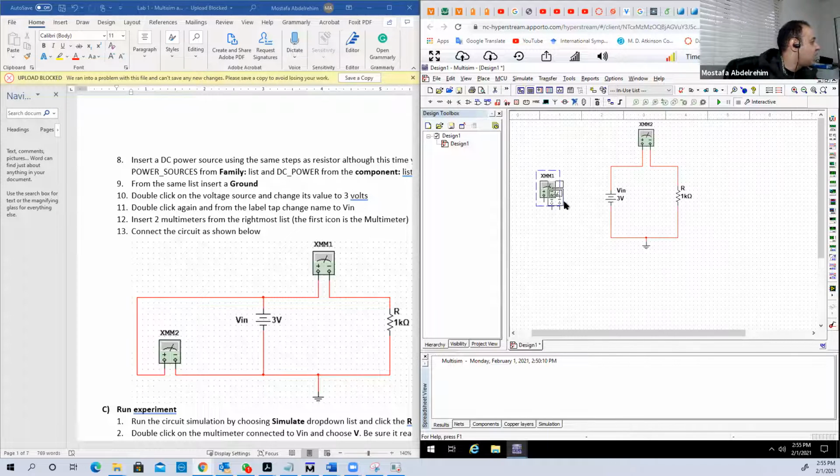One last thing is we're going to connect the voltmeter here. The multimeter, which will work as a voltmeter, in parallel with the voltage source. So negative goes with the negative, which is the ground, and positive goes with the positive. Just do it in 2 steps, just to make it pretty. Okay, good. Oops. You can just fix it like this. It's not a big deal.